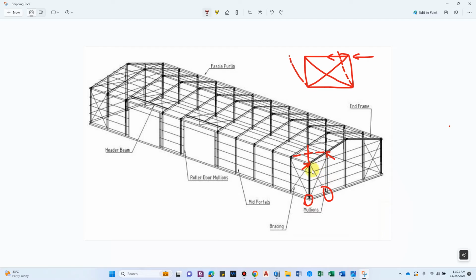The other thing that we have to consider is, we have transferred the lateral force of this face directly to the footing. So the connection that we provide here with the bolt action, the design must be sufficient to take that horizontal load which is transferred to this footing.